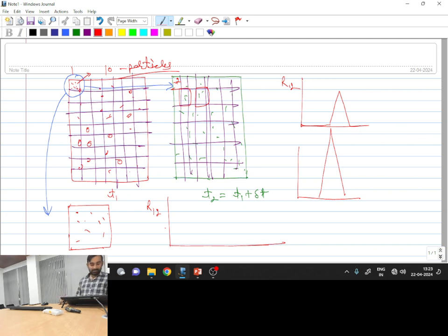Okay. So like this, when you will be cross correlating, say the cross correlation with this image is highest. Now you know the grid locations of this frame. You know the grid locations of this one. So you can see what are the displacements delta x and delta y of this grid with reference to this origin point. Once you know the displacements, then delta x by t and delta y by t will be giving you the velocity.